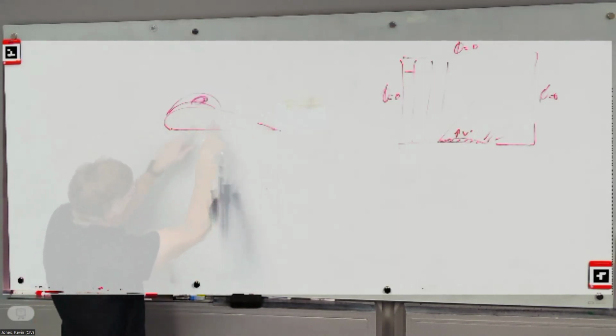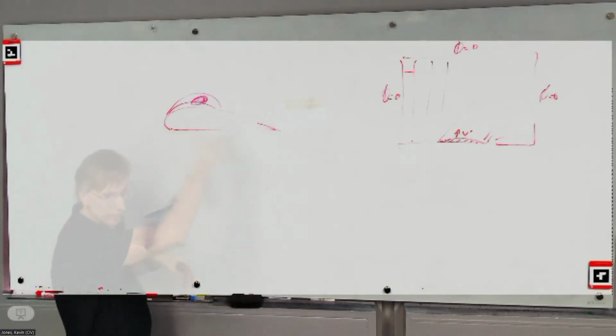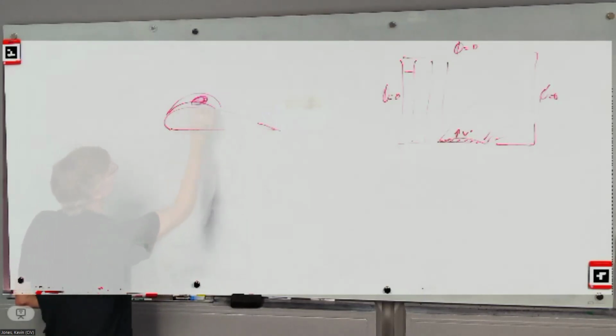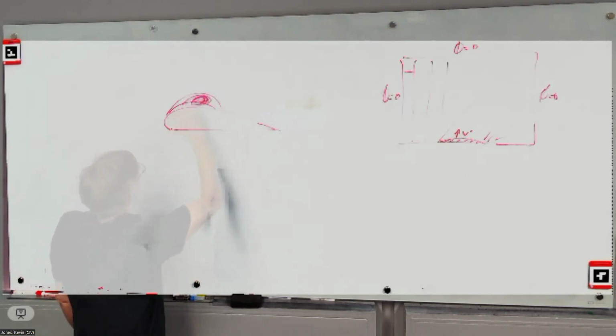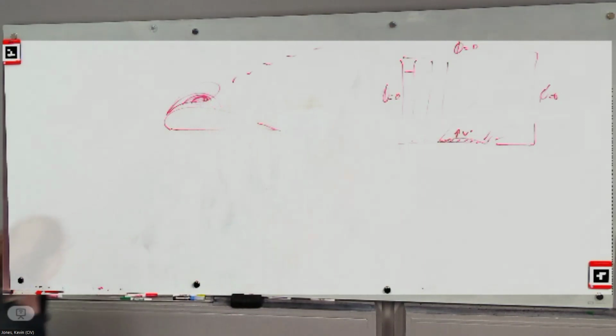I don't know if this is completely accurate, but one way to interpret this is that you've got bound circulation inside the wing that's creating the lift on the wing. And some of that circulation goes into this big separation bubble here. It's like a big vortex that's churning in here, and it grows over time. And at some point, it separates from the wing and then eventually goes off on its own and travels downstream.